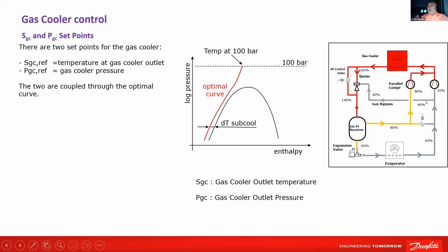I'll explain it this way. Please hold your question. Evaporator, this is the MT compressor sucking. Forget this compressor for now. Gas cooler, then the gas will go through this valve or ejector. We'll go to the ejector and come to the intermediate receiver. Because of the pressure difference, the ejector will lift some of the gas from the MT suction, this evaporator suction, and dump it into intermediate pressure. This will give a pressure lift of up to 11 bar, depending on the evaporating and gas cooler pressures.